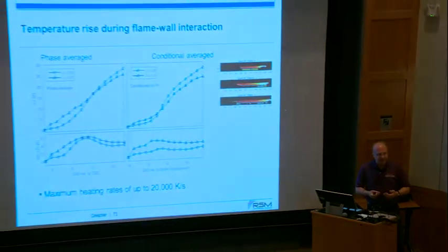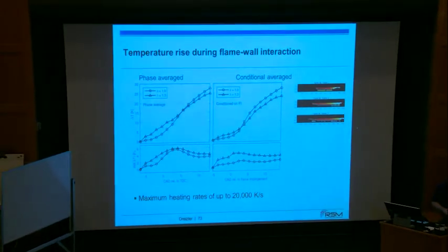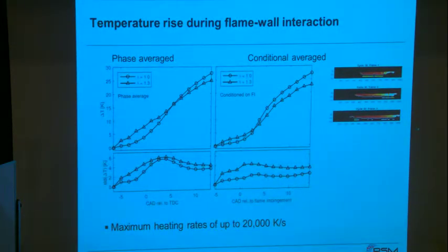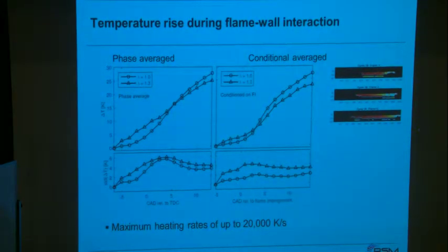This is limited here to more of a proof of concept, and of course it can be used in conjunction with simulations to validate models that predict that correctly. If you want to do that in an engine that is really operating close to full load, then you have to do something different with the optical access. And that can be done, of course. If you have resources, you would come up with a minimally invasive optical access, where you have more or less the full metal engine and only small bores, with endoscopes that can sustain and survive even higher mean effective pressures and higher temperatures.